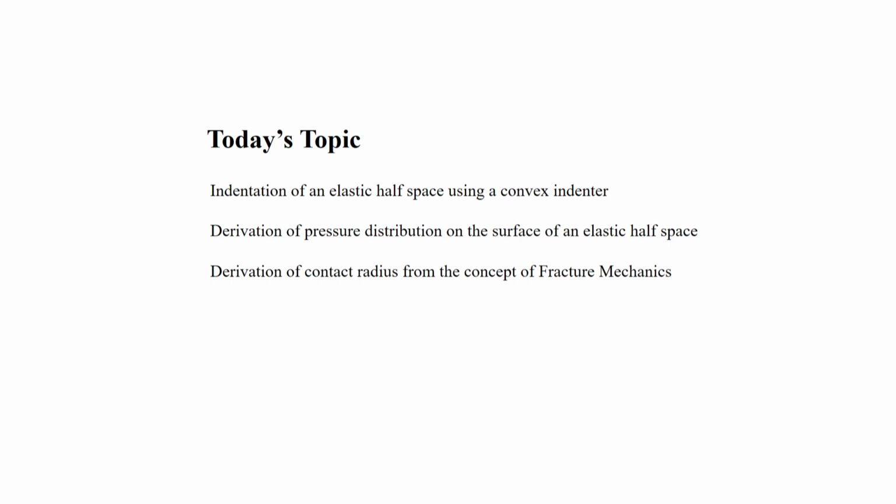We will discuss the convex indenter today, and in the next few lectures I will discuss the concave indenter as well. For the convex indenter we will not derive it using the Hertz mechanics approximations. Instead, we will use ideas from fracture mechanics to derive the expression for work of adhesion, and we will use a theory developed by Abel for determining the pressure distribution. I will just go into it right away.